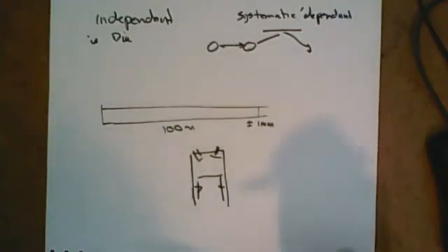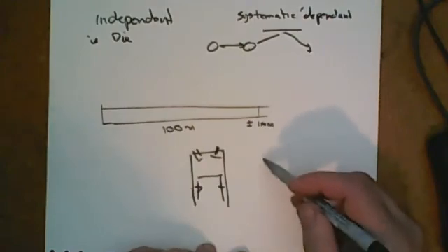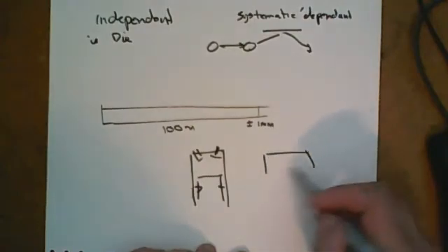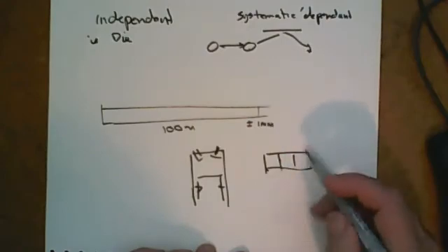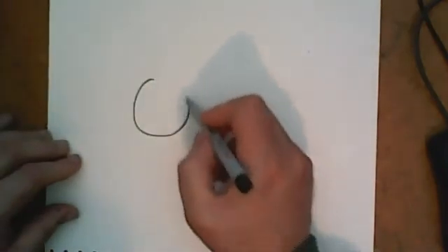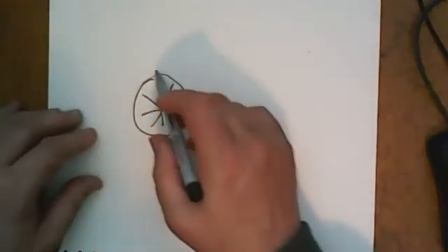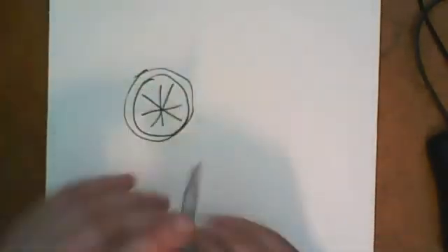And we use tricks like that all the time in engineering. If you want to fit stuff, I mean, they've done this for hundreds of years. If you want to fit something like an iron tire onto a wooden horse carriage, so say, or onto a wheel, a wooden spoke wheel, what you do is you heat up, the steel expands, you cool it, and then it contracts down. Oh, okay, that's beside the point.